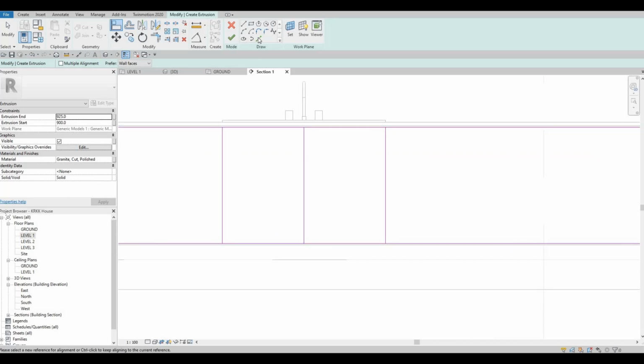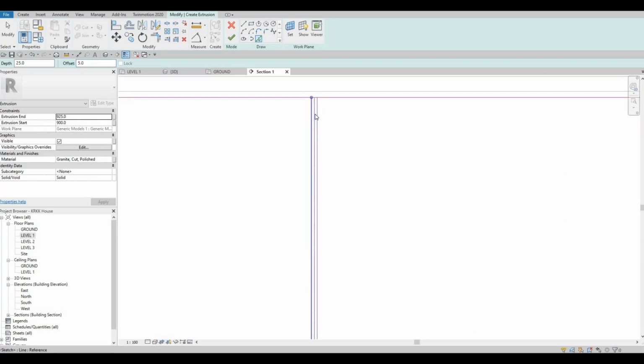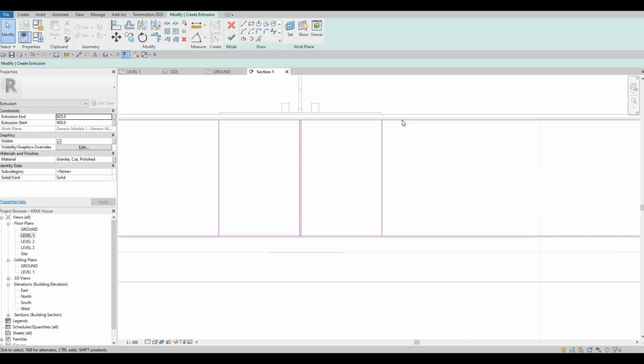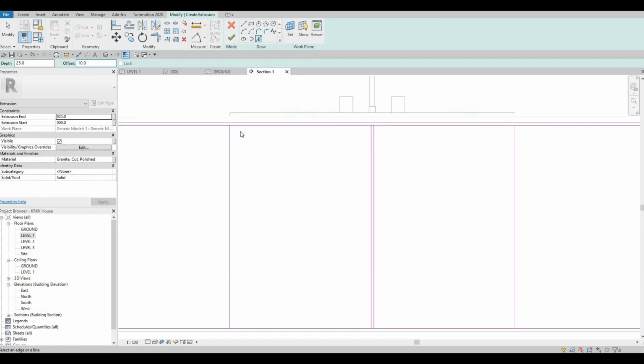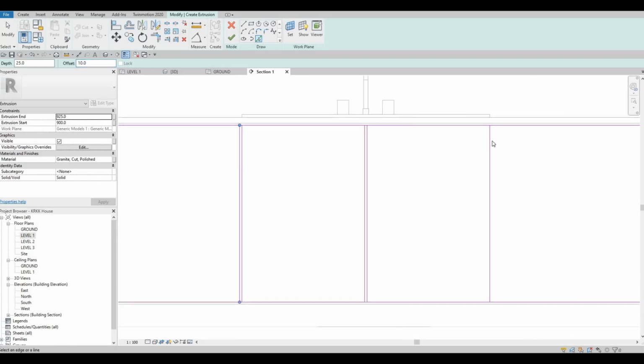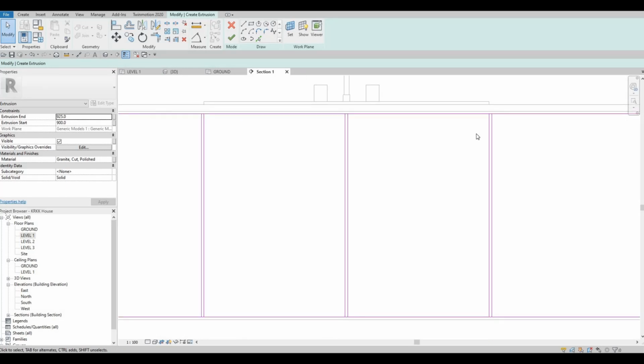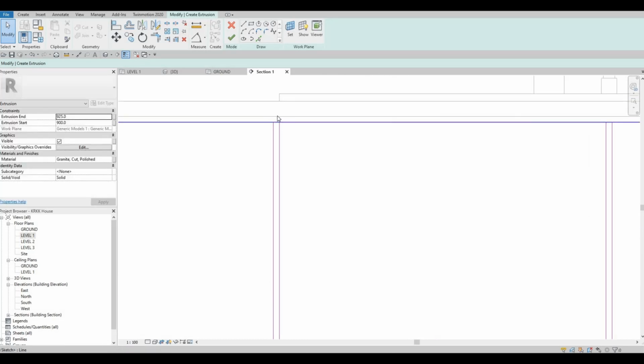Now that looks good. I'm going to select this pick line and then click on 5 offset from the middle, and then delete the ones in the middle. Press escape and delete the ones in the middle, and then here, pick line, I want it offset 10. So maintain the 10, and then we need to click on split face later on, or split line.